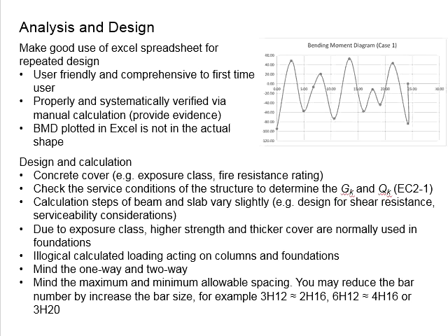This is especially when you deal with the design for the shear resistance. Due to the smaller cross-section of the beam, the calculation step for the shear resistance is normally more tedious, where you really need to check the shear angle between 22 degrees to 45 degrees. That means definitely the beam sections do not have sufficient resistance by the concrete on the shear.